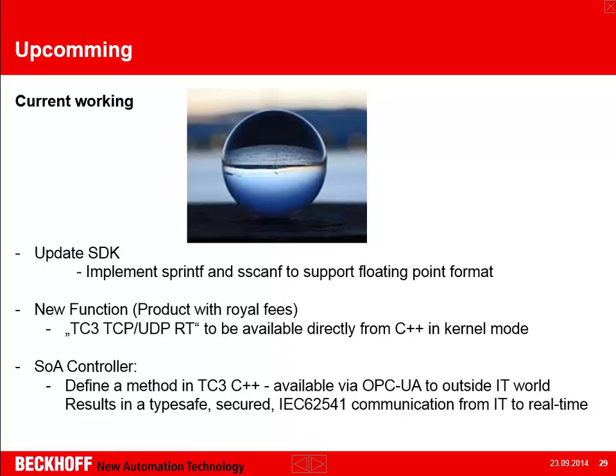This is an international IEC standard, OPC UA, and this allows whichever OPC UA client in the world on whichever operating system to browse to the OPC UA namespace, find the method, figure out the input-output parameters of that method, and then even execute that method.